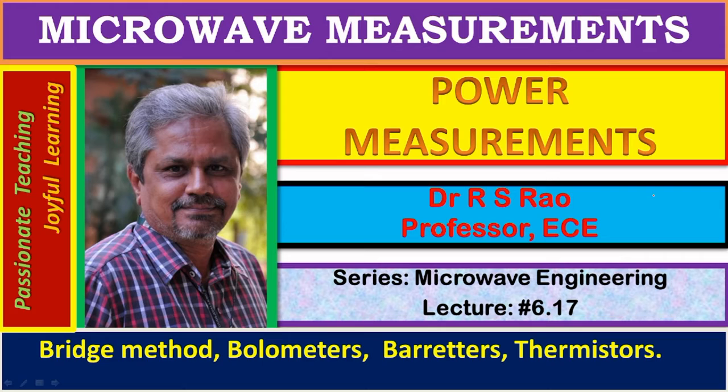To measure microwave power, an instrument is designed, and it is available in the laboratories. It is called a power meter. It is able to give an indication regarding microwave power. It is basically a bridge circuit. In one of its arms, there exists a temperature sensitive element.